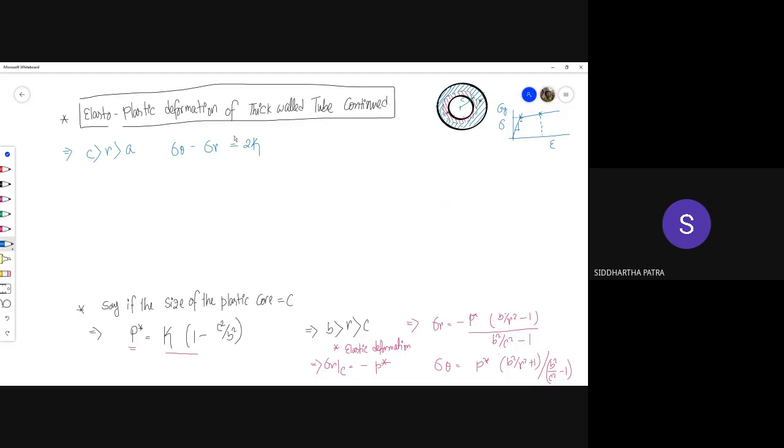All of this is coming from, as you can recall, the maximum shear stress theory. We established that sigma theta is the highest principal stress and sigma r is the lowest principal stress. Sigma z comes in between in every possible scenario, and there are no shear stresses. So essentially, the r theta z becomes the principal coordinates.